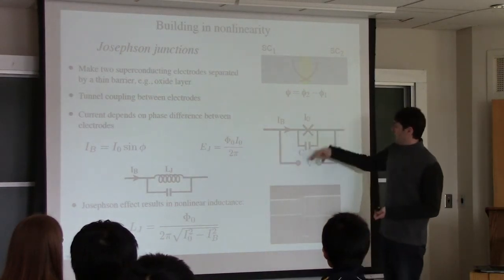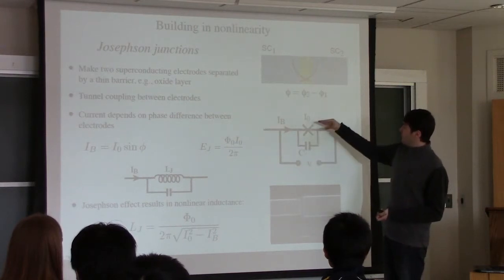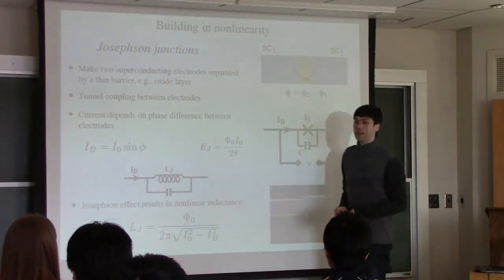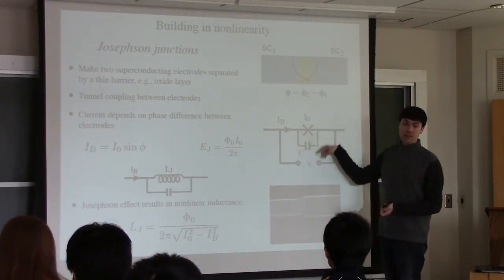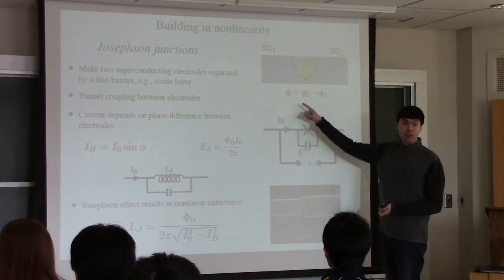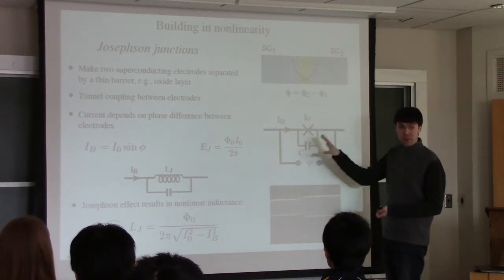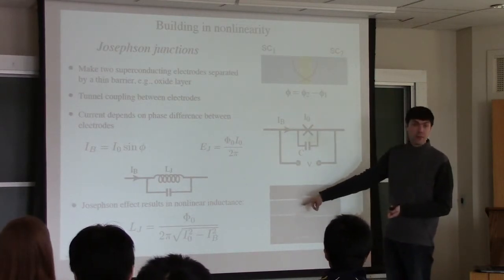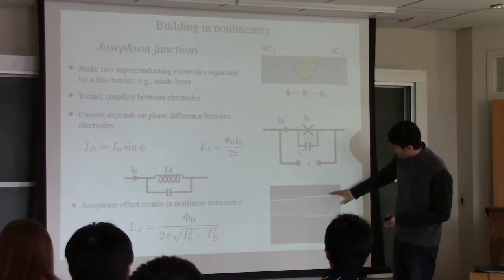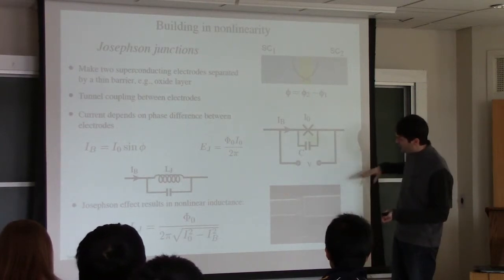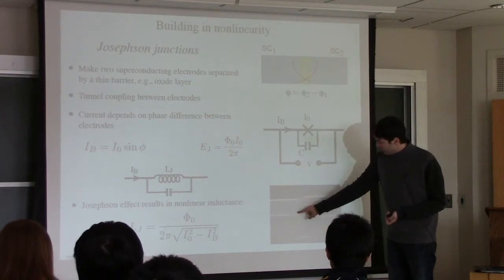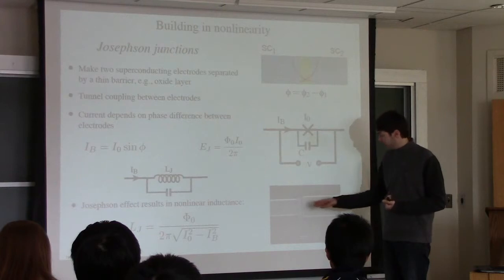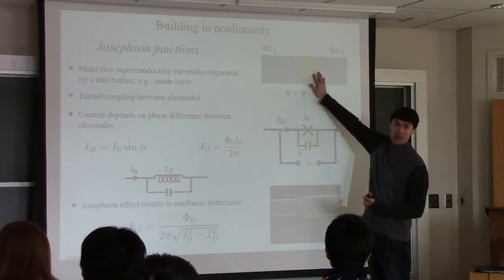We discussed this circuit diagram, that the Josephson junction is represented by this cross, and it's an element that has this dependence, but there could also be a capacitance here, resistance, and that's an RSJ model that gives you a washboard potential. And that's from the previous lecture. A common technology for that is an overlap shadow technique. You can see here two pieces of aluminum evaporated like that and like that, making an overlap, a Josephson junction, and in between we oxidize to create a tunnel barrier. So this is the direct implementation of this diagram.